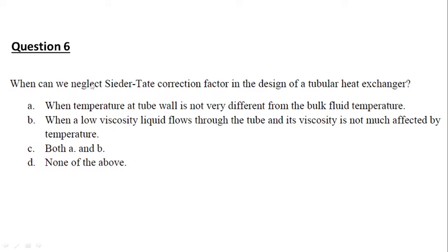So we can neglect the Sieder-Tate correction. The Sieder-Tate factor will be important only when the temperature at the wall is very far from the bulk fluid temperature. So in option A, when the temperature of the wall is not very different from the bulk temperature, we can neglect the Sieder-Tate factor.